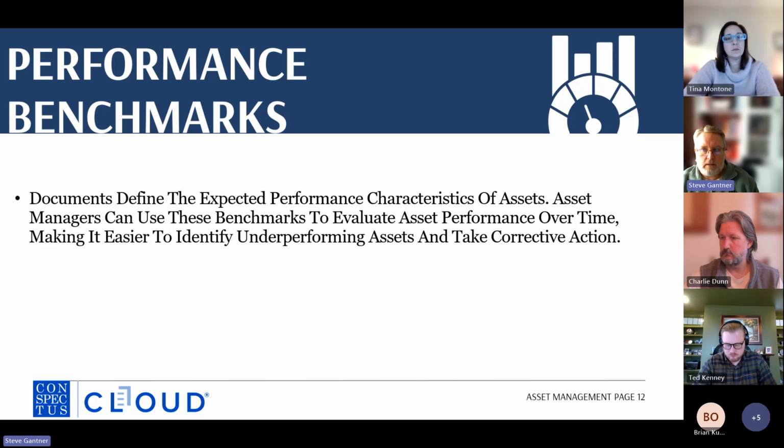So you're tracking throughout the entire life cycle how your materials should be functioning, how your assembly should be functioning, and when you should be looking at possibly replacing parts or replacing the entire assembly. And it's not duplicating O&M materials, because O&M in that instance is operations and maintenance manuals, which basically just tells you how to maintain and run the stuff. It doesn't tell you how it was designed.